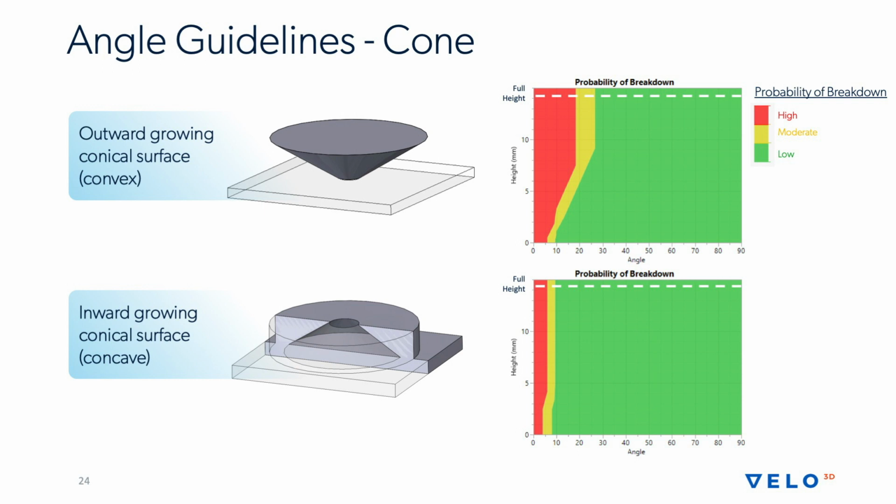On top of that, you have a secondary low angle surface, or skin surface, that's being applied. That's basically melting a ring and solidifying, and it's warping with a similar vector, in that it's warping kind of in and up. And those two stress vectors work together to make a leading edge that really wants to warp up. And so your minimum angle that you can print safely is higher in a lot of cases. It really depends on how long you propagate this, because the stress accumulates over many layers.